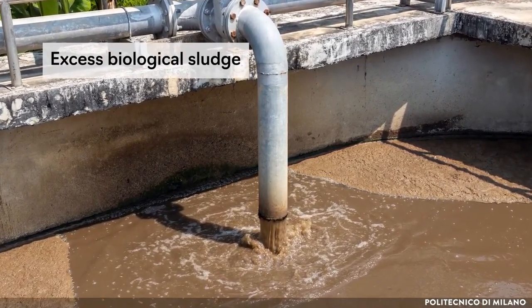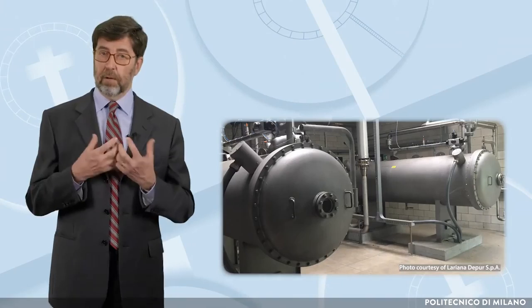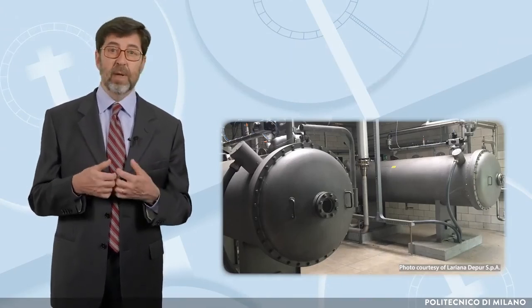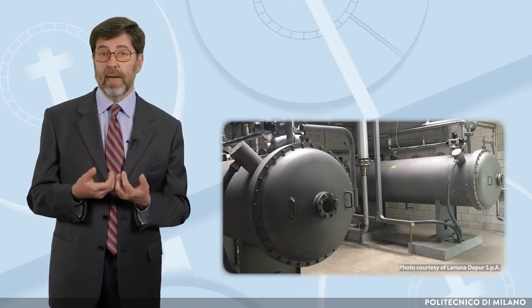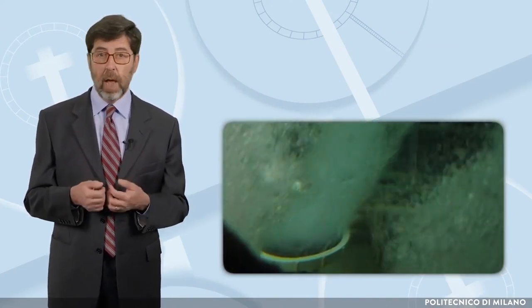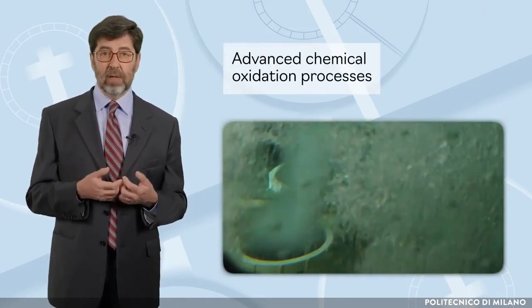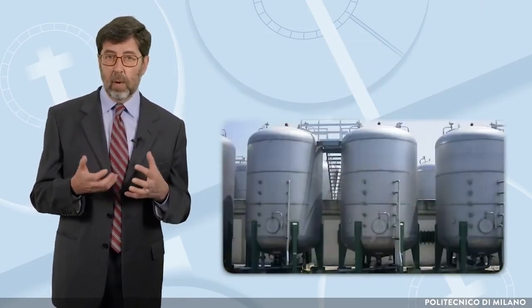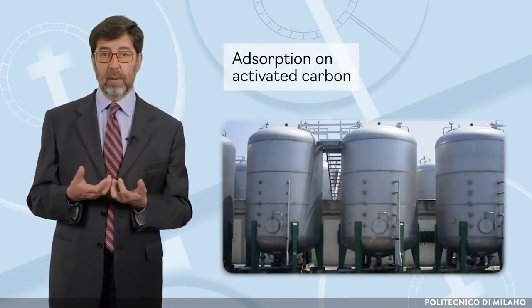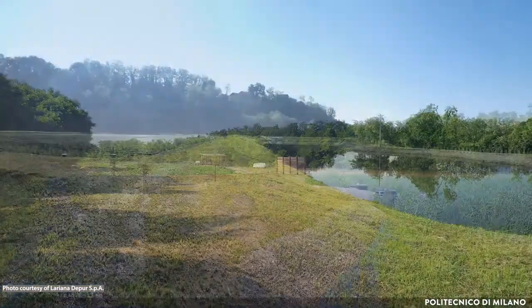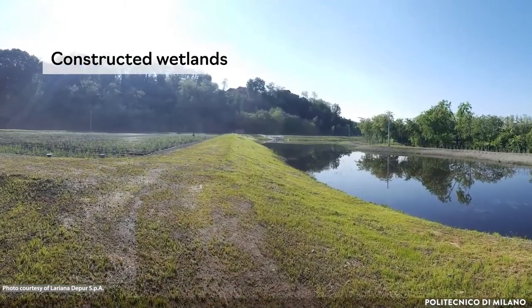But all this may not be enough. Surfactants and trace contaminants, such as metabolites of pharmaceuticals or other contaminants of emerging concern, may be removed by adding advanced chemical oxidation processes and/or adsorption on activated carbon. The purified effluent can be further refined in constructed wetlands for final depuration.